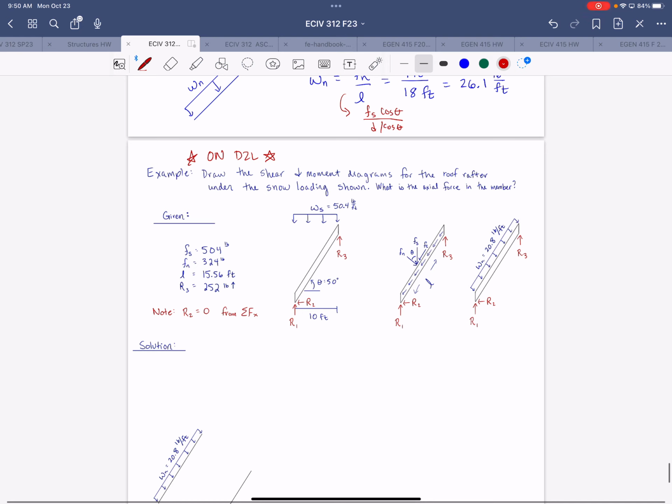You do need to think about that buildup of snow and the lateral pressure that it can apply to the walls of your structure. That's definitely something you would need to think about when you have a steep roof or a roof where snow will slide off. It has the potential to build up, and that can have structural impacts, but it can also have other impacts related to snow melt and water and things like that. Those are all things that need to be considered with snow.